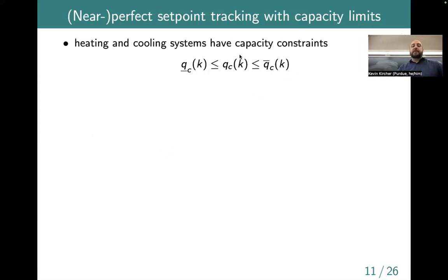Okay, so that's probably the simplest way. It's maybe not that accurate because, so for example, if we're in heating mode and we took the set point over there, say it's at 72 Fahrenheit, and we dropped it to 65, the perfect tracking model would say that, at the next time step, 5 minutes from now or an hour from now, whatever it is, that it would become exactly 65 degrees in this room. Which is not really how the system would behave, because you'd probably need air conditioning in order to reduce the temperature in this room that quickly.